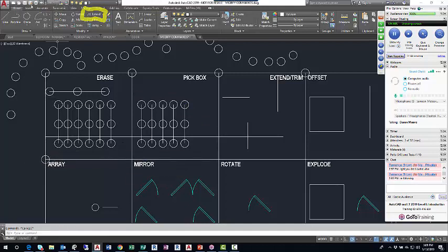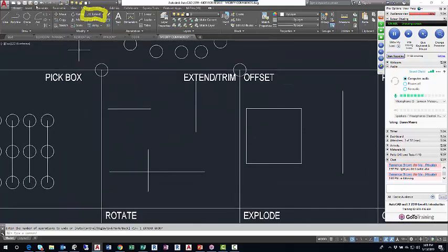I'll hit escape. But for the most part, if I'm working in close contact, if you will, in an enclosed area more or less, extend, enter or right click, and then just hover and left click, hover, get a preview, like the preview, accept the preview, like so. Hover, preview, like it, click it. I mean, you won't always like it. You don't have to click it, but I'm just kind of refining the look of my drawing.